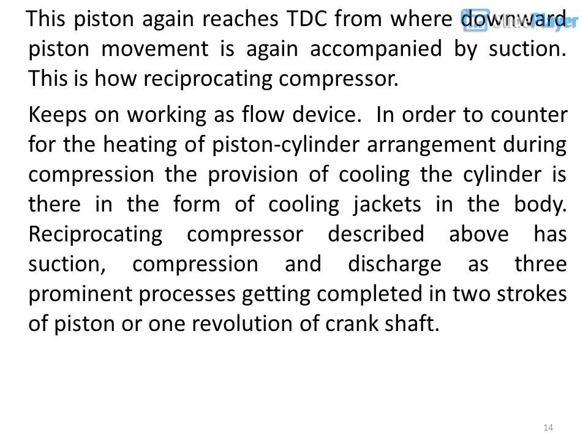In order to counter the heating of the piston-cylinder arrangement during compression, provision for cooling the cylinder is there in the form of cooling jackets in the body. The reciprocating compressor described above has suction, compression and discharge as 3 prominent processes getting completed in 2 strokes of the piston, or 1 revolution of the crankshaft.